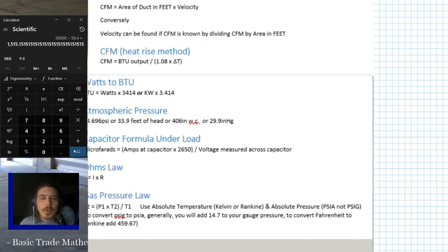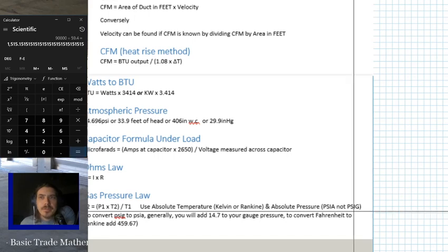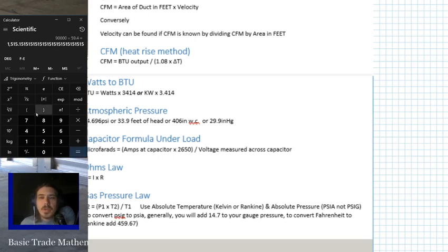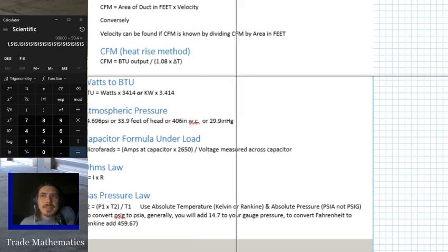Now, a critical part to remember if you're doing that is if you're trying to figure out the CFM when it kicks into cooling, then you need to make sure that fan's on high speed and not low speed for the furnace. So if you're going to bother doing it, you might as well check what your CFM is on low speed, furnace speed, and then check what the CFM is on high speed for cooling, just so you know what the two numbers are. You might as well take them both. But typically, you're more worried about that delta T on a furnace.